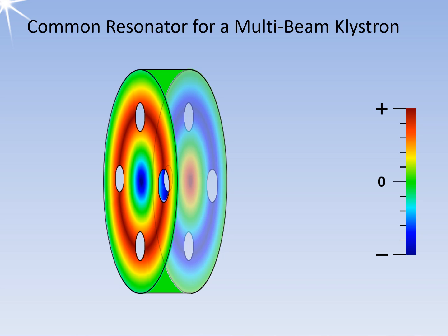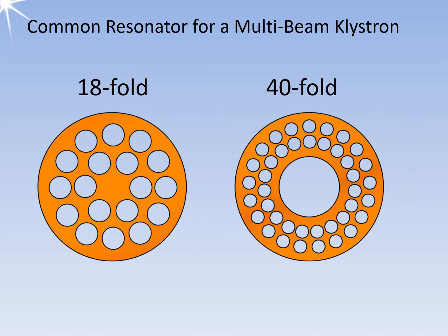To ensure that the maximum strength of the electric field effectively interacts with the electron beams, the resonator is operated at its first harmonic wave. This choice also increases the size of the resonator, as its diameter becomes one whole wavelength instead of half a wavelength. The 4-beam klystron depicted here is infrequently used. In practice, a significantly larger number of electron beams is typically employed. Higher modes are also possible, as are other resonator shapes, such as a coaxial form.